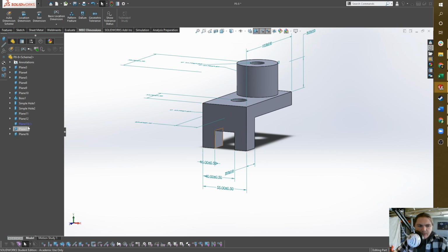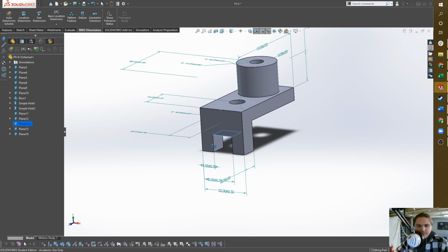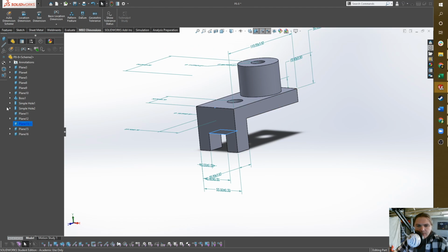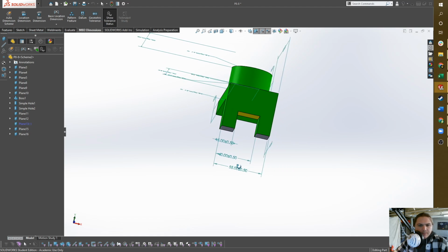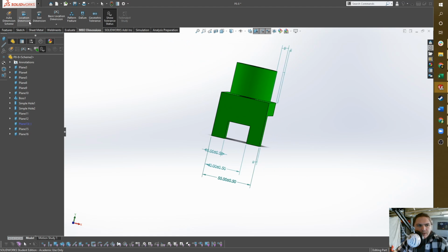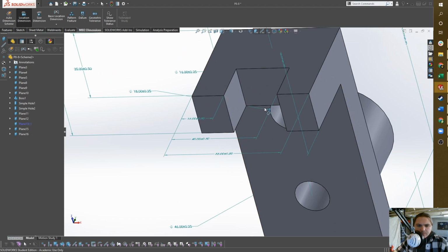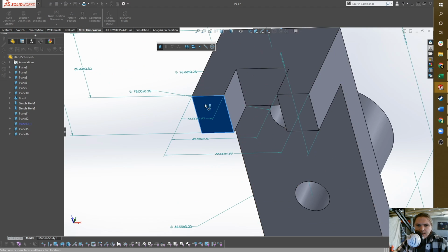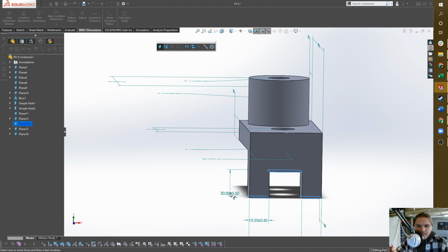So when you're underdefined, you'll see the surfaces that need work or some sort of dimension to fully define them, and there'll be kind of a purplish color over in the tree on the side. So I click on that, we got gray and yellow there. Let's do a size location, or a location dimension, on there. I'm going to select this surface, and then up here on the toolbar I'm going to create a compound plane. That basically means planes that are in line with each other. So I'm going to select both of them, hit check, and then I'll dimension up to here, and then place it.